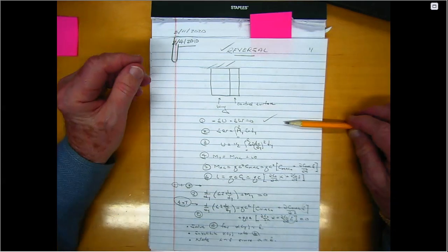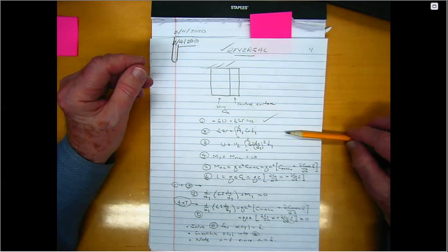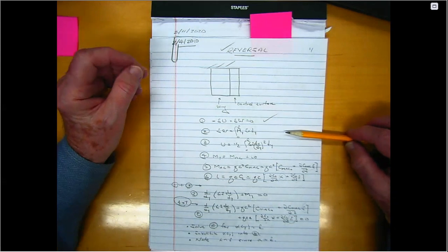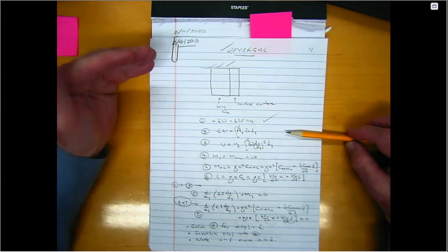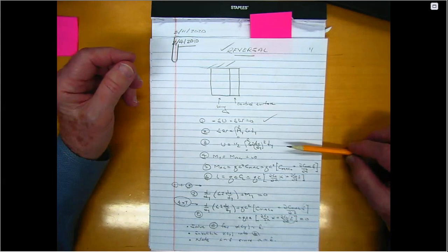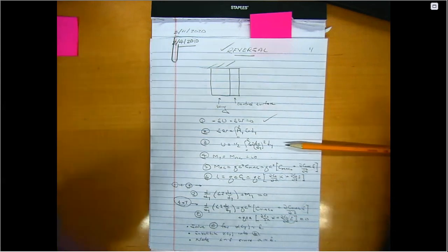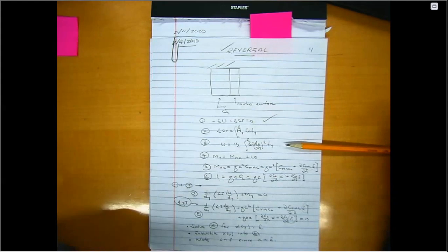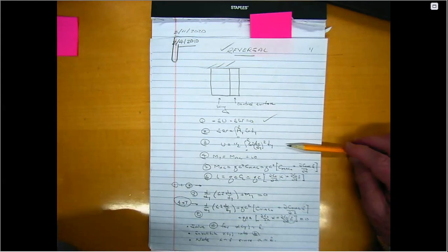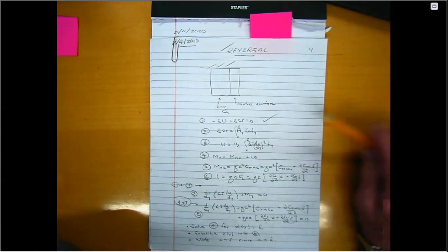You need to write down the expression for virtual work, and that is going to be essentially the same as you had before when you did the typical section with springs, except now the aerodynamic forces are per unit span, right? Now the potential energy, rather than being the spring constant times alpha squared times 1/2, is now a distributed potential energy, taking into account that GJ is the torsional stiffness of the wing.